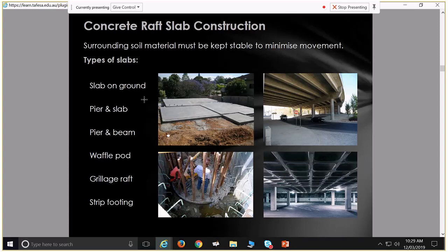But you're still going to get some strength by having all those sections filled in. But let's say we had a solid slab which is 400 mil thick, or a slab that was 100 mil thick with 300 deep beams on it. That solid one is still going to be stronger in the main than something with the beams. But for the amount of concrete, for the amount of expense, it's not going to be that much stronger. So it's not a cost-effective strength.